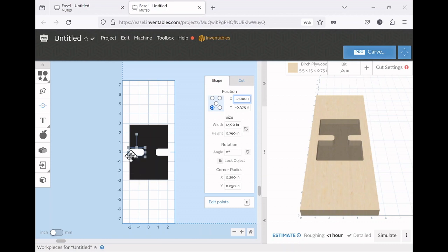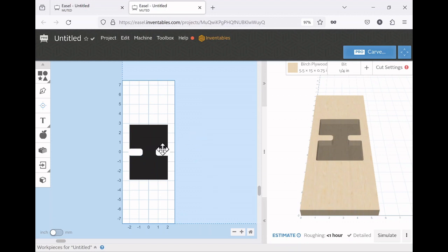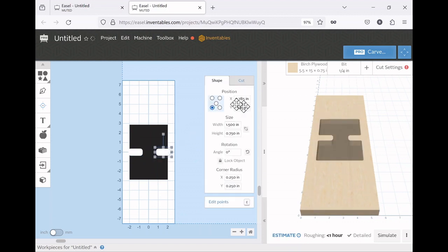But I want you to look right here. See the round over that we did, the radius that we put in the corner here is still visible there. So we're going to shift it a little further over to eliminate that. So we'll go over another 1/8 of an inch, and that will eliminate that problem. All right. And then we're going to do the same on the right one. We're going to click on this, and this time we're going to reference the lower right corner. And X here, instead of being -2.125, is going to be +2.125. Now we have them both lined up where we want.